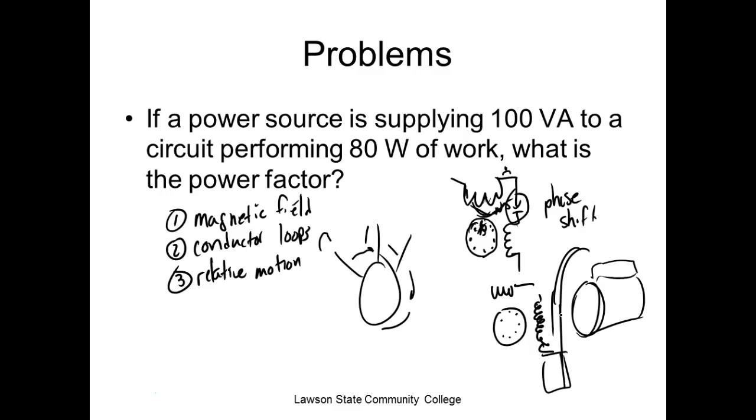These are where we would deliberately add capacitance to the circuit, or deliberately add inductance to the circuit, so we can create a phase shift to cause the single phase motors to run. To start, right? You understand that? By the way, another way you can tell if it's your start capacitor, if you have access to the shaft and you spin it and it runs in whatever direction you spin it in, then that's definitely the start capacitor.